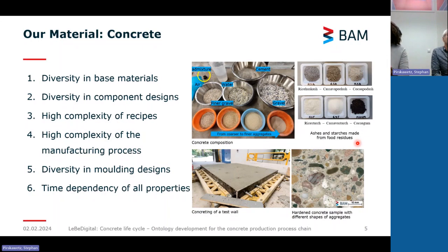Everything happens in the manufacture, and then the end concrete is just brought to the construction site. And this manufacturing process of the precast concrete will be totally different from the one for a ready-mix concrete, or Transportbeton in German, where concrete is brought to the construction site in hydration. Like, it's still hydrating, it's not yet hardened. And also the manufacturing process is different according to the fresh concrete characteristics we want to have, like the workability or even the density of the fresh concrete.